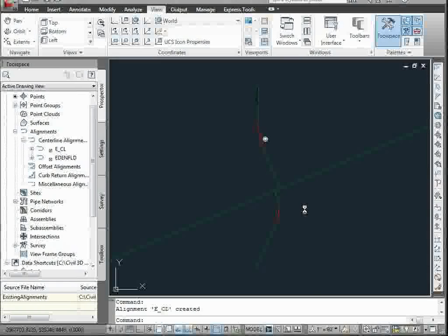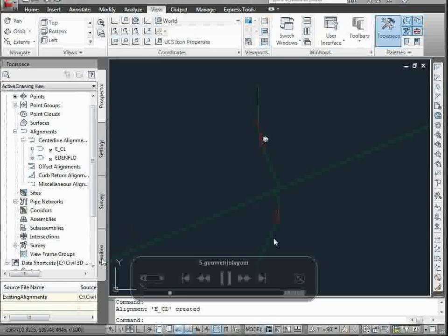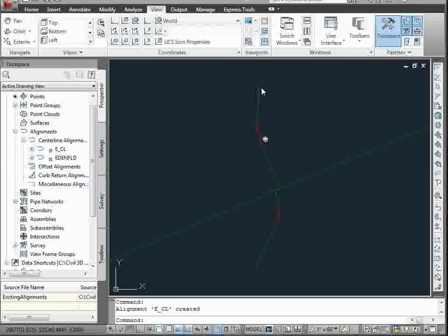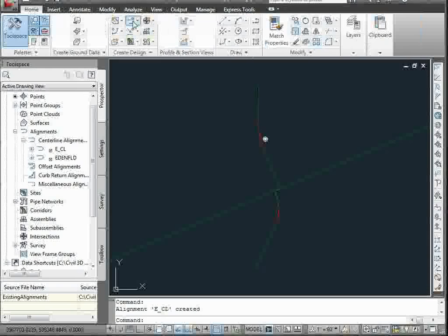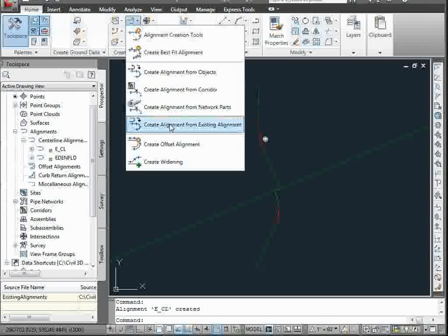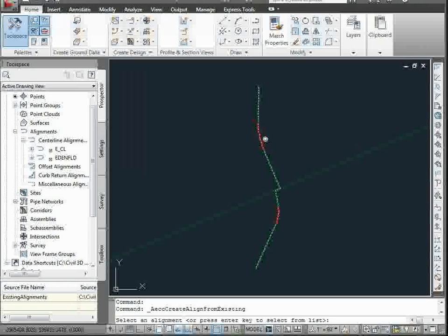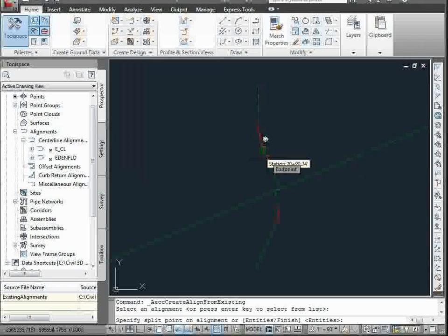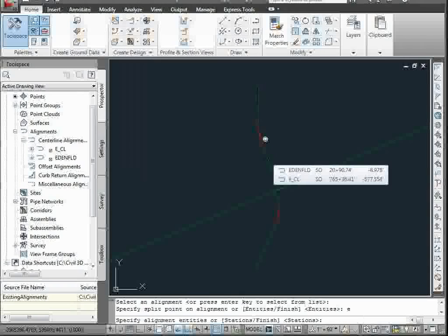So we're going to use this data, run through here now, and I'm going to move ahead a little bit. But one of the criteria is, and we all know this with road design, number one, we'd like to have a single point of intersection of the two roadways. So we're going to establish that. Number two is that we're going to want to have a particular minimum angle of deflection at the intersection, such as an 80-degree angle.